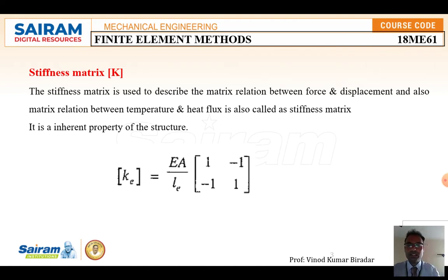Normally stiffness is nothing but force divided by deflection. In every FEM problem there will be a force acting, and depending on that we calculate the displacement, stresses, strain, all those things. The definition of the stiffness matrix is: it describes the matrix relationship between the force and the displacement. That is called the stiffness matrix.